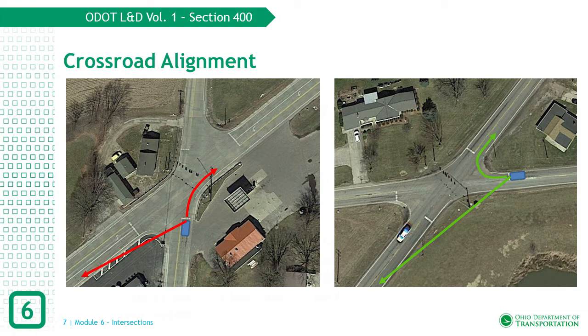The image on the left shows the acute angle on the driver's right side. This angle forces a driver to turn a large degree to see an approaching vehicle. Their own vehicle can block the sight line due to the size of their windows. Finally, this movement can be especially difficult for older drivers who may have experienced a decline in their head or neck mobility. Right turns on red may not be appropriate to permit at this location.